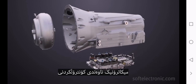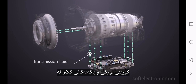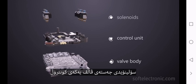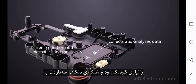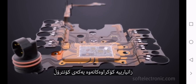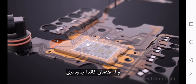The mechatronic is the control center of the gearbox. Its task is to manage the torque converter and the clutch packs in the gearbox via the transmission fluid under specific pressure. It consists of three main components: control unit, valve body, solenoids. The control unit collects and analyzes data about the current condition of the mechatronics and fluid via speed sensors, temperature sensors, and pressure sensors. From the gathered information, the control unit optimizes and executes the program for gear changing and at the same time monitors for errors in the electronics and mechanics.